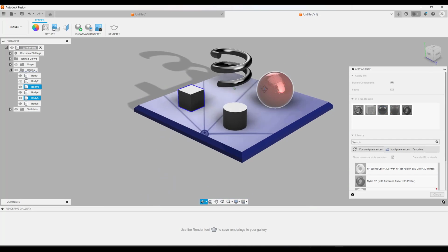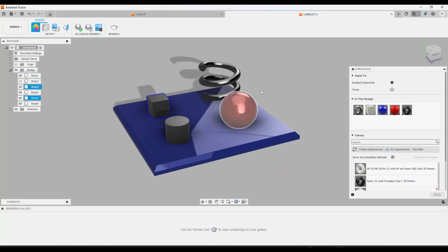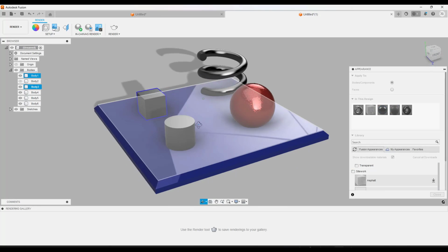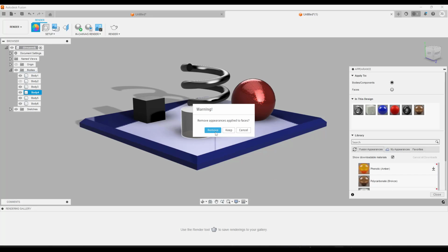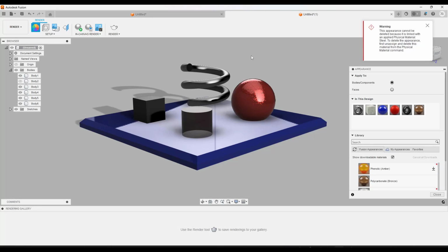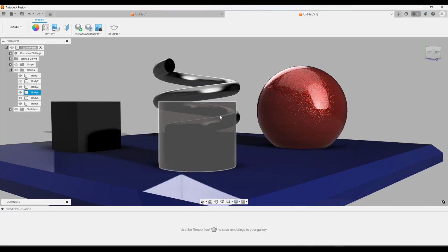Those map settings and the settings contained inside of the materials are going to basically adjust the way those materials work. And so sometimes you've got materials that are actually transparent. So if I go into the transparent settings right here, notice how there are presets for things like the phenolic, the polycarbonate, and let's pick one of those. Let's pick the polycarbonate material right here. So I'm just going to download that, and I'm going to drop it on this box, and I'm going to remove the previous material. And so notice how with this polycarbonate material, you can actually see through it.